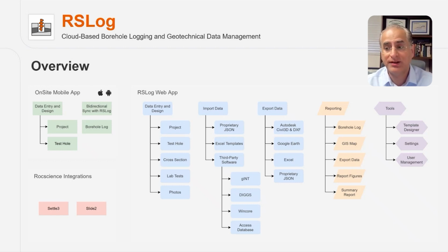A lot of customizations on the settings page. One thing to mention about user management is that the access level of each user can be defined by you. So if you want to block the access of, say, your junior engineers to a log template design, just to make sure that a borehole log template that you made won't be accidentally deleted or changed, then you can block some users' access to different pages.